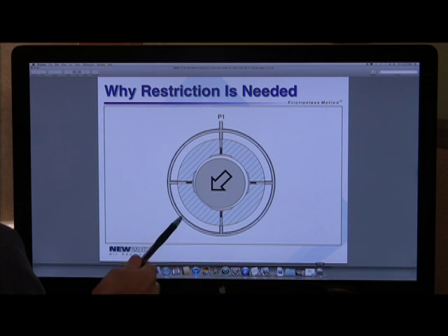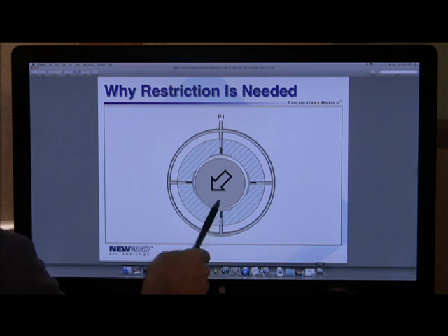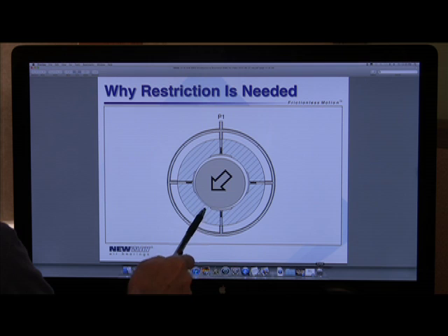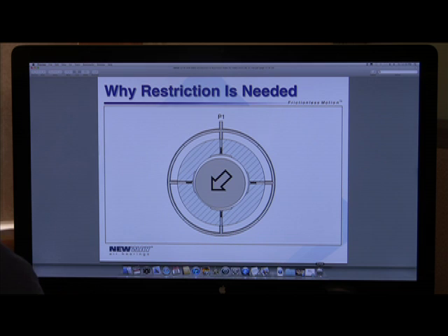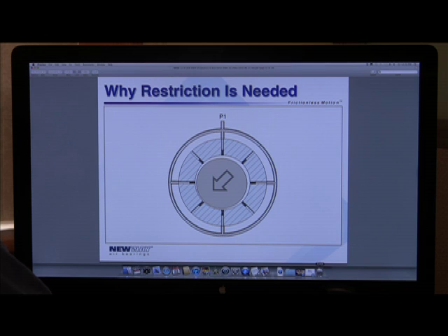Now when you have a load on the shaft that's not pointed directly at an orifice, you wind up having a hard time trying to get the pressure to actually go to where it needs to be in order to support this load. So what do designers do? They add more orifices. Now this is technically superior, but it's also very expensive to try to compensate a bearing this way.